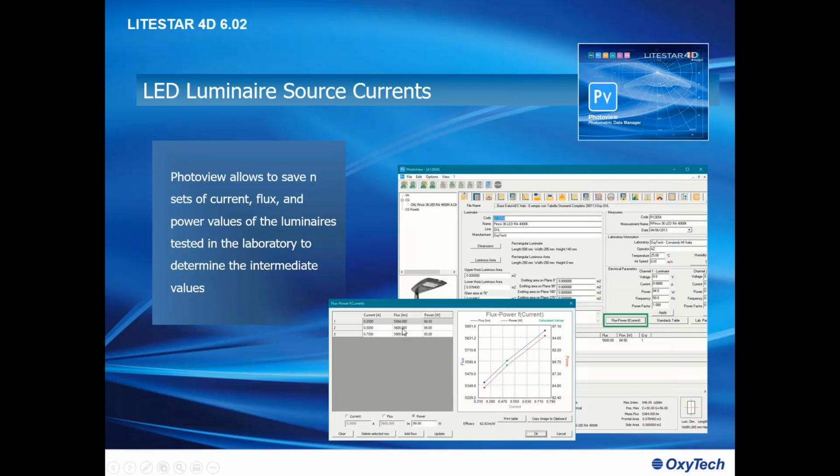You read the lux value at gamma 0, you convert it to intensity, and you create the ratio between the intensity value at gamma 0 corresponding to 350 milliamps and this one. And the ratio can be applied directly to the flux because it's proportional.